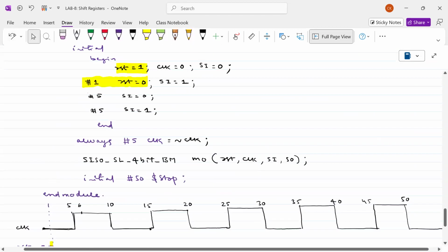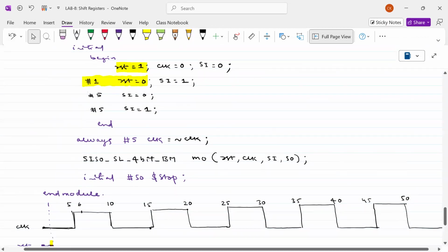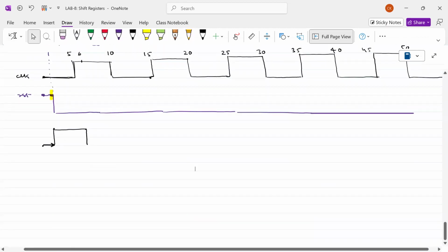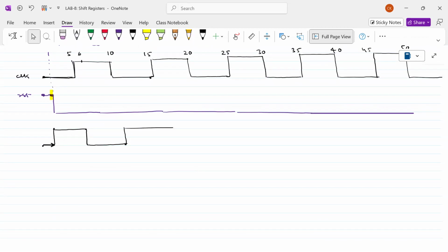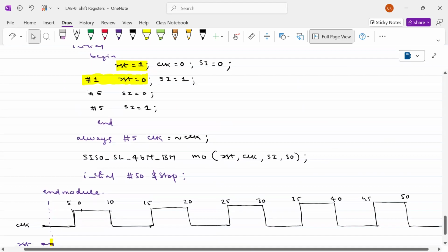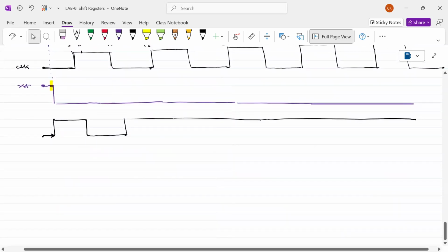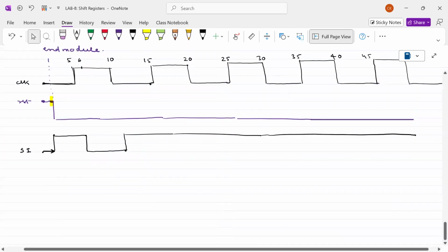Right. Next, what does it have to do? Add another 5 nanoseconds. That means at 11 nanoseconds, it becomes 1. So let's go to 11 nanoseconds, till this point. It is 1, and this is 1 forever, because if I'm not changing anything, it remains there. That's what I have written in my test bench. This is called serial in data. What is my expected output?